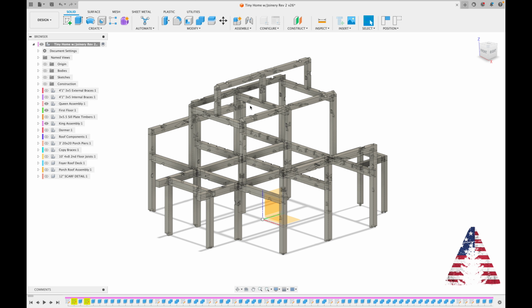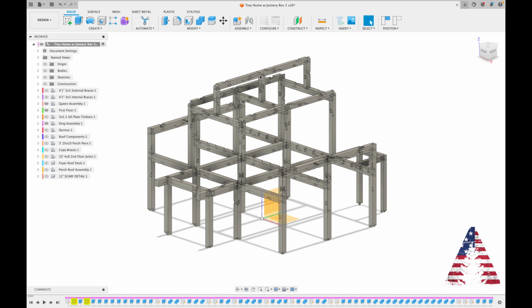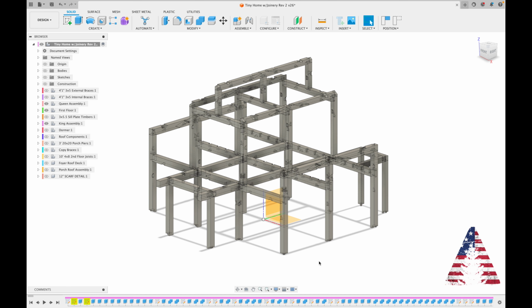So we have to enter this whole process first with pre-assembly and test fitting everything, labeling stuff for the braces, making sure that when we know a brace is good here between this scarfed section and this king post, when we put it back together it goes in the same place so that it's square and plumb in its final home. So the plan is to start from a top to bottom approach, and I'll get to why we chose that at the end.